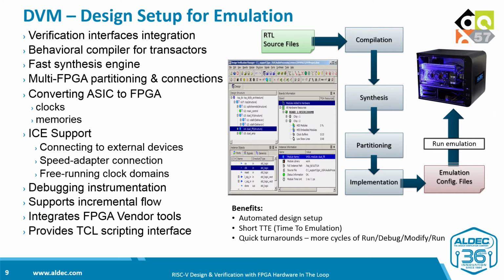In emulation mode, that also includes simulation acceleration, DVM integrates verification interface with your design and provides behavioral compiler to convert transactors, monitors and similar test bench components to FPGA. So your RTL code is compiled and converted to netlist using Aldec's fast synthesis engine.